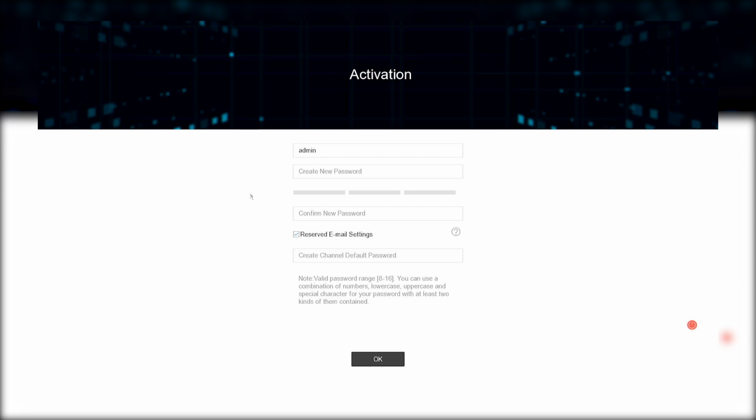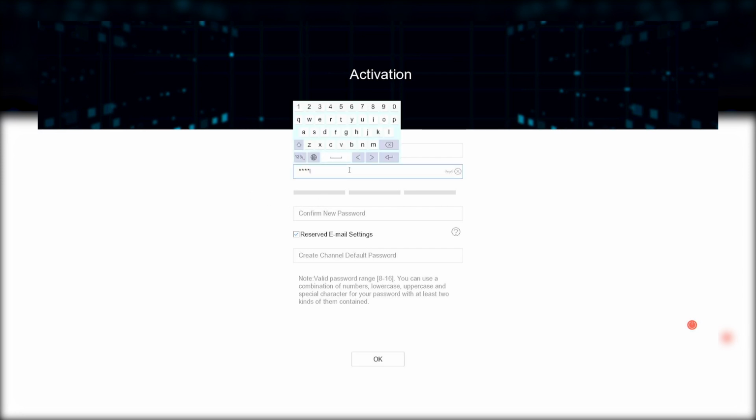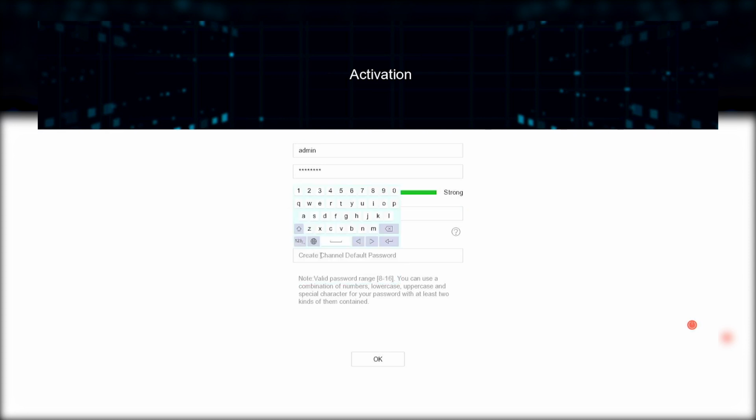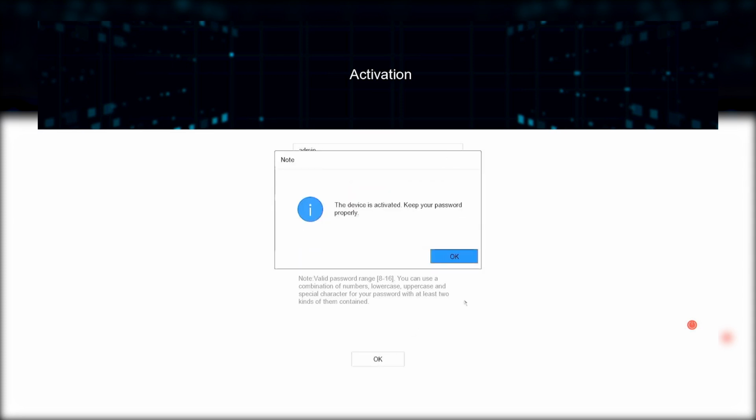Once the desired resolution has been set, you can begin the activation process. From here, we'll be giving the NVR a specific password. We recommend using the same password used in the initialization of the camera in all fields. Select OK to confirm your password at the bottom of the screen. A prompt will then appear requesting a valid email. Please input your email and select OK.